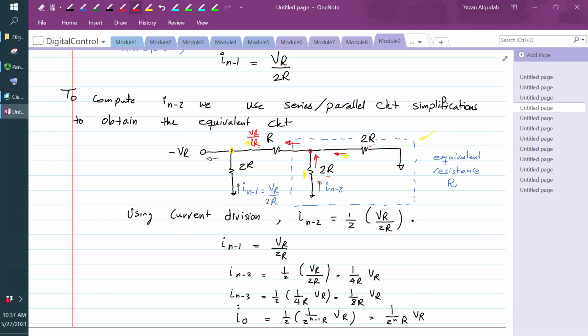So therefore, whether I switch this resistor on and off is going to determine the total current contribution. But you can see that the contribution of each current depends on the position of that current. So therefore, the currents will only contribute to I total if the respective switch, Bn minus 1 to B0, is connected to the op-amp.